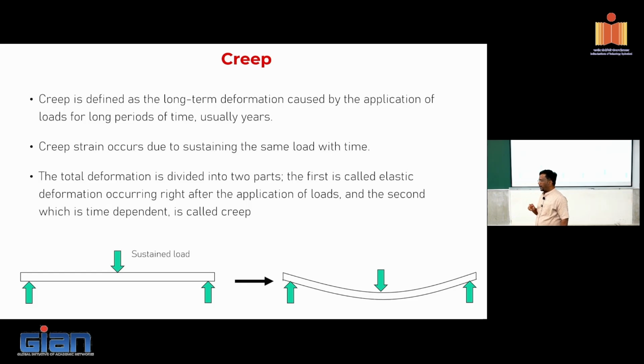Okay, sir. But addition of such a high percentage of fibers will lead to very low workability. Correct. Very high dosage of admixtures will also reduce the strength of the concrete, right? Correct. So you have to tweak it. That's a very good question. The higher the fiber dosage, the more workability goes down. Then I need to put in more superplasticizer, and with more superplasticizer, the mix will not set. So you have to tweak your mix design. That's why mix design is very important. It depends upon your application. So let me leave it there.